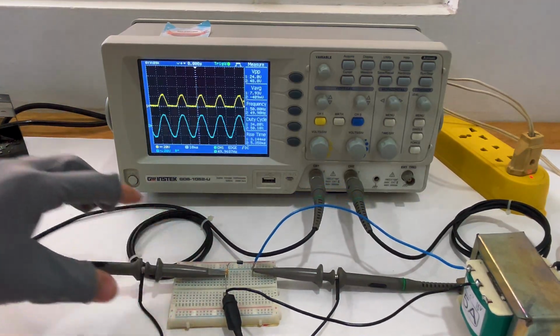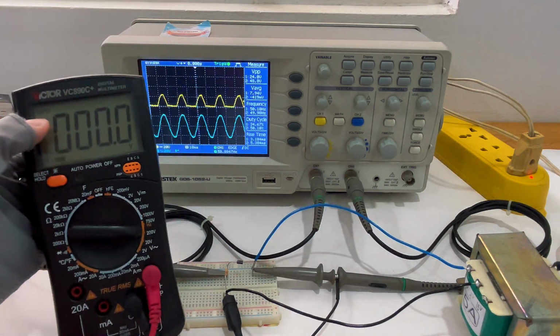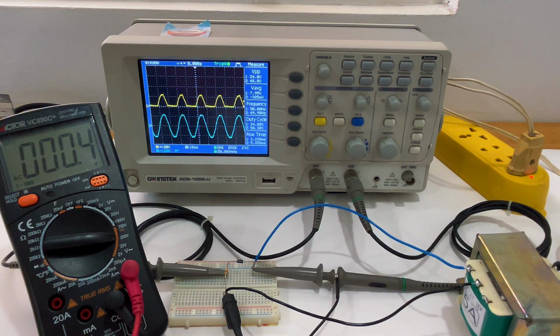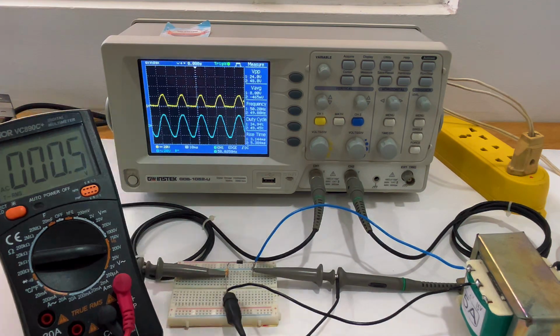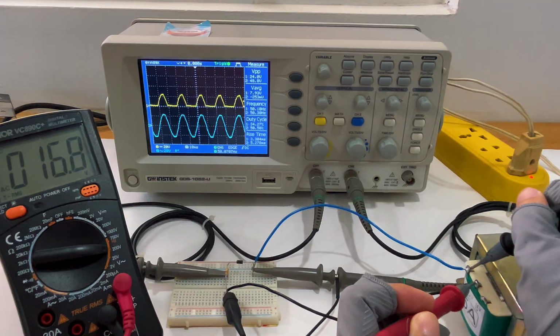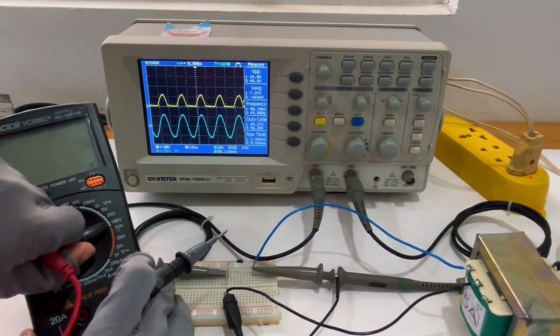Next, I use a digital multimeter to measure the input and output voltages. You can refer back to the video for details on how the output voltage is calculated. The diode used in this experiment is a 1N4007, which has a voltage drop of approximately 0.6 volts.